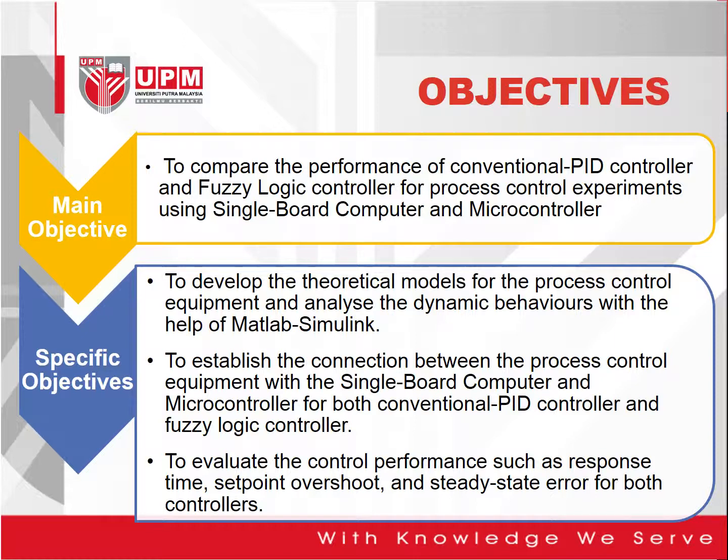The specific objectives are to develop the theoretical models for process control equipment and analyze the dynamic behaviors with the help of MATLAB Simulink. Also, it is to establish the connection between the process control equipment with the single board computer and microcontroller for both conventional PID controller and fuzzy logic controller. Thirdly, it is to evaluate the control performance such as response time, set point overshoot, and steady-state error for both controllers.